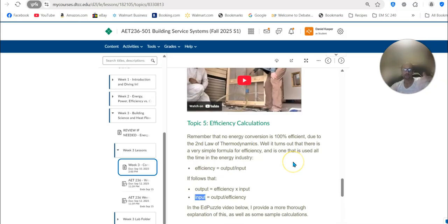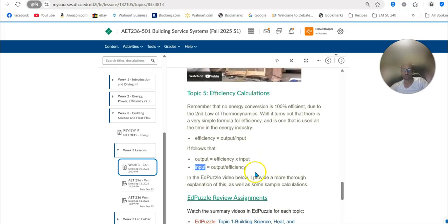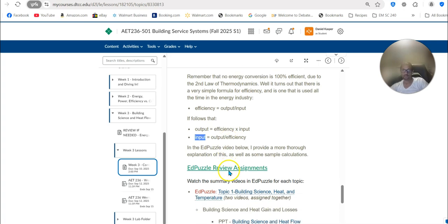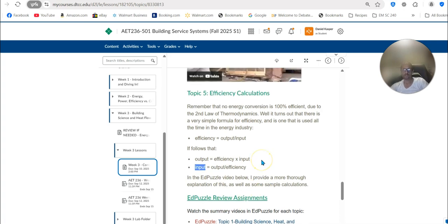And then ultimately calculate a heating load through a surface and then calculate how much energy would be needed, how many units of a given fuel source would be needed to provide the heat that space demands.